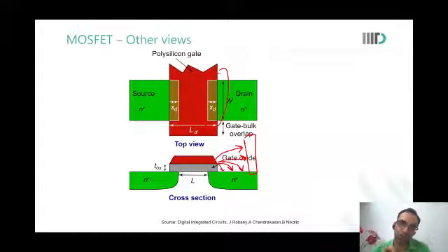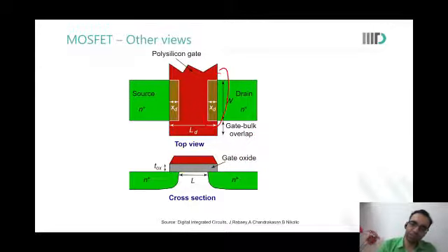Gagandeep talked about just one component, which is the overlap capacitance. But there is this other component of capacitance between gate and drain, which would come with the gate to contact coupling and the gate to diffusion layer coupling. So this diffusion layer coupling, I'm not able to get exactly what. Exactly, this is what I showed. There is a dielectric here. Let us remove this. This is all dielectric.